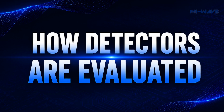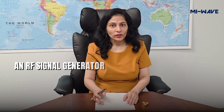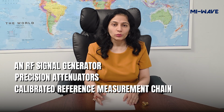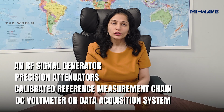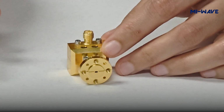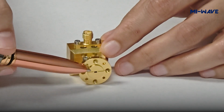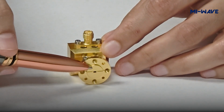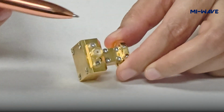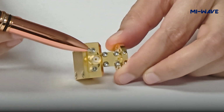So how are detectors evaluated? Amplitude detectors are typically characterized using standard RF laboratory equipment. This often includes an RF signal generator, precision attenuators, a calibrated reference measurement chain, and a DC voltmeter and data acquisition system. The process is straightforward. A known RF power is applied to the detector at the waveguide port, and the resulting DC output voltage is measured at the coaxial port.